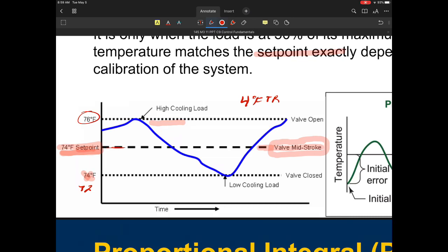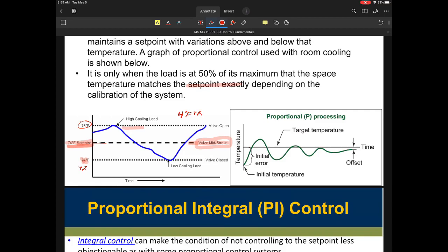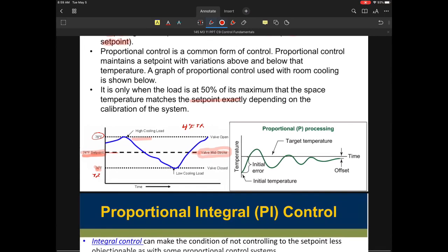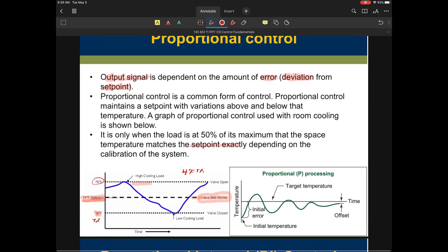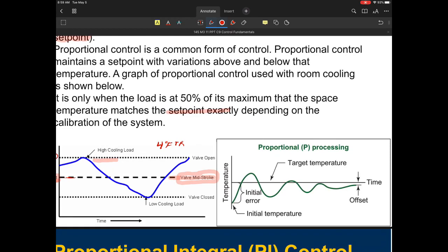That actually rarely happens. There are very few valves that are that linear when you're talking about control valve operation. It's no different than even an economizer actuator. If you give an economizer 50% and make it 50% open, you don't get 50% of the air. It's just going to be significantly higher than that. It's a matter of how linear the application is based on its selection. But this is a common issue, and it's something you have to be aware of.